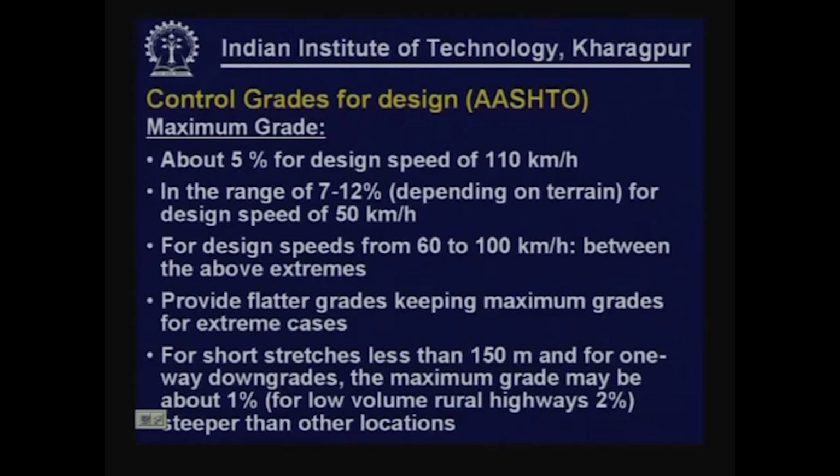We should try to provide flatter grades as far as possible. The maximum allowable grade should not be used all the time for design. We should try to provide flatter grades, keeping the maximum grades for extreme situations, where terrain conditions are difficult or site-specific problems are there. So, we should keep the extreme values for those cases.